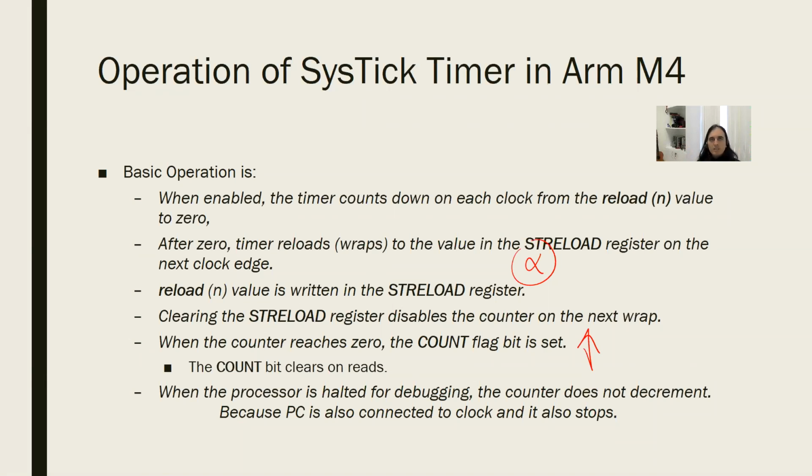So in debugging, the timer will stop. That's why we'll be able to check the timer. However, if you want to get the exact amount of time between two button presses, for example, you cannot do it in debugging mode, because in real time, the time will pass, but the clock will stop. So in debugging mode, we'll have some special analysis and so on. You'll see. So be careful. In debugging, the clock stops. That's why the timer also stops. So we have a basic idea of how to make it work. If we knew the addresses of the control registers, we could do it. Let's do it.